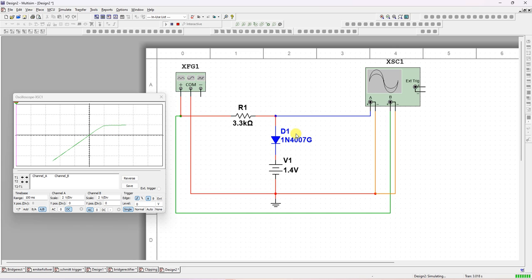Okay. So this is about the positive peak clipper. In the positive peak clipper, you have to connect the diode vertically. Diode drop is 0.6. For however much voltage you want, add 0.6 to that. For example, for 2 volts, 0.6 plus 1.4. For 3 volts, 0.6 plus 2.4. For 4 volts, 0.6 plus 3.4. So change it and you will get the output. Okay. Thank you.